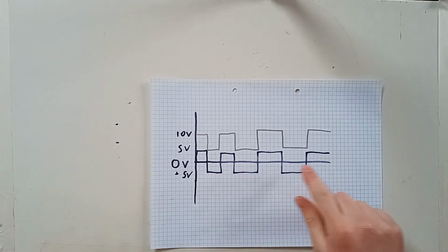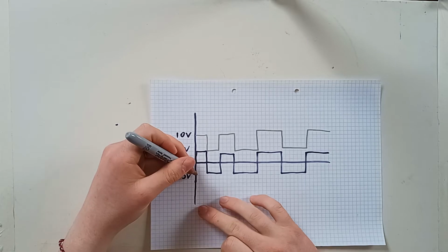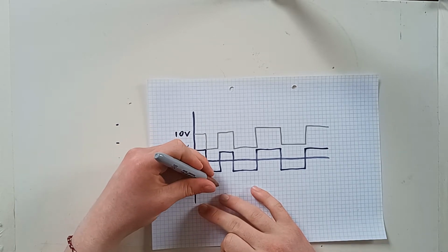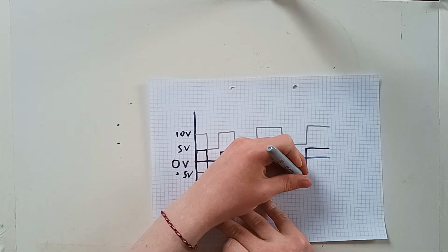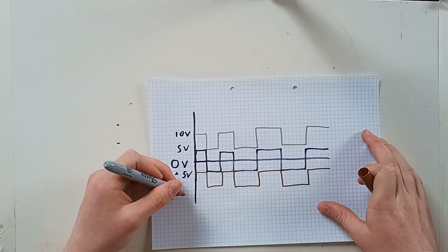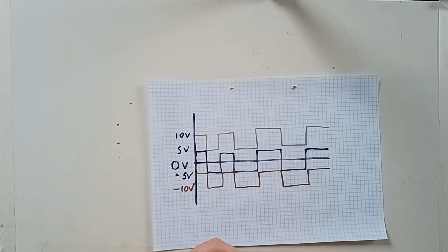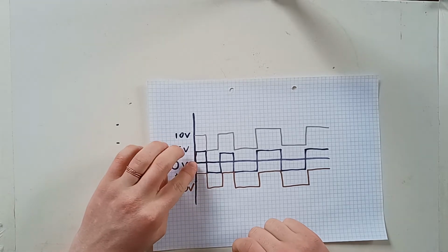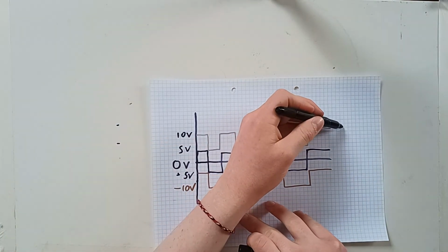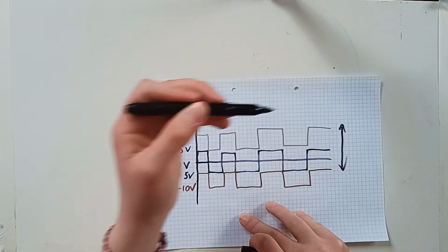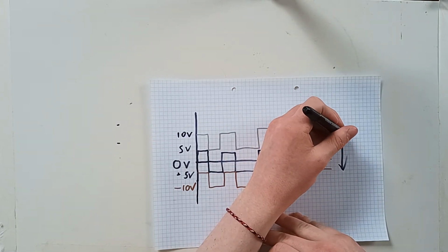So you're splitting this original signal down two paths and adding your offset there. And then if we say the troughs of this one are minus 10 volts. So that means that on average, with a 5 volt oscillation each way, we are getting a bias between these two signals of 15 volts.